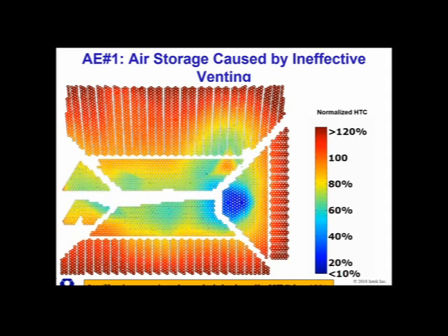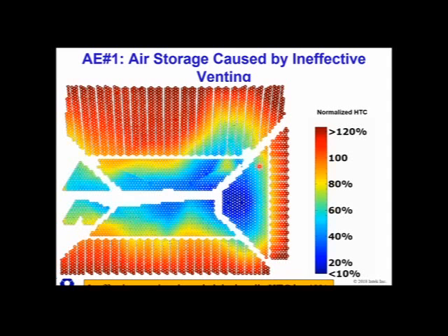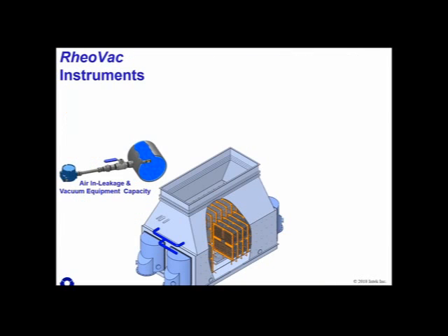And so we're going to animate this, and you can probably already anticipate what's going to happen. This blue is going to grow as the pump capacity gets not shut off, but goes lower. And so now this airbound zone has grown and a stagnant zone has reached out and come over here. So now hopefully you have a picture in your head of how air envelops these bundles. And that's going to be really important to troubleshooting the condenser, especially air in-leakage problems.